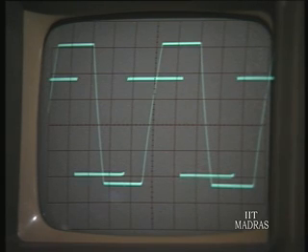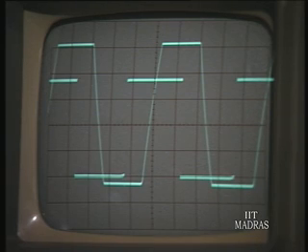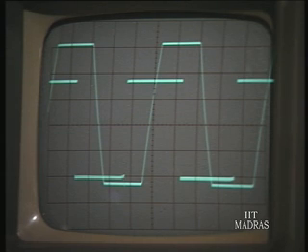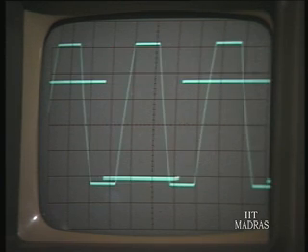Because the output and the input have a phase shift of 90 degrees, you can see that clearly. Now please slowly change. See, it is tracking, and the phase shift, now it has gone out of lock.